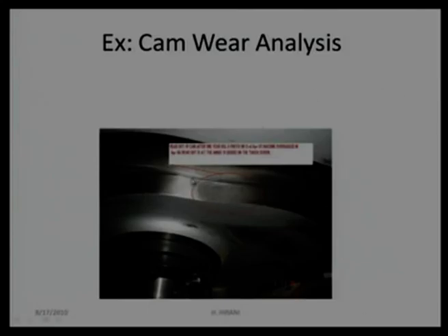And this portion shows clearly the number of pits, and if I take some reference axis at 0 degree here and rotate by 270 degree, this kind of wear occurs roughly at 270 plus or minus some degree. If I take the reference axis over here, then this will turn out to be around 90 degree. That is why this heading says this wear has occurred at 91 degrees. That means there was a reference axis over here and 91 degrees over here, if I assume the rotational motion is clockwise.